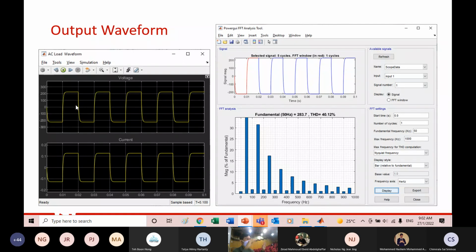our AC is a sinusoidal waveform, right? Beautiful. So meaning that it should not have any harmonic. But this one is a square wave. Like I say, it's good enough to power small, low power devices. It won't cause much problem. And for stand alone, you cannot connect this to the grid. If you connect it straight away, TNB side will trip.